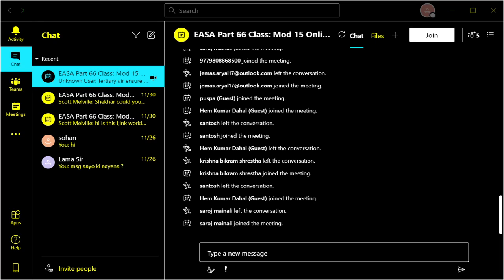Things you have to check for when you fit these is make sure the little pins here, grab them with a nail, make sure they don't come out. And even the magnets, some of the magnets are push fit in, sometimes they fall out. So again, just a little gentle feel, make sure they're okay. And ensure they have 2 seals fitted.